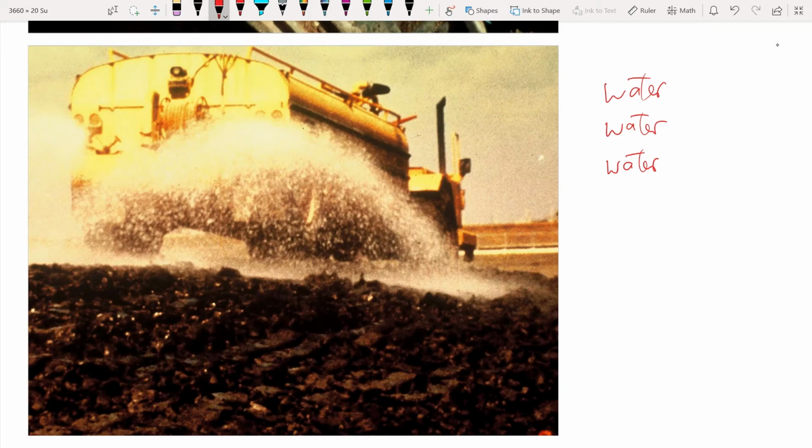If you want to increase the compaction effort, you can increase the weight of the compaction machines, or the compaction loading, or you can compact the site by having the machines or vehicles go through the site more and more times, with more passes.